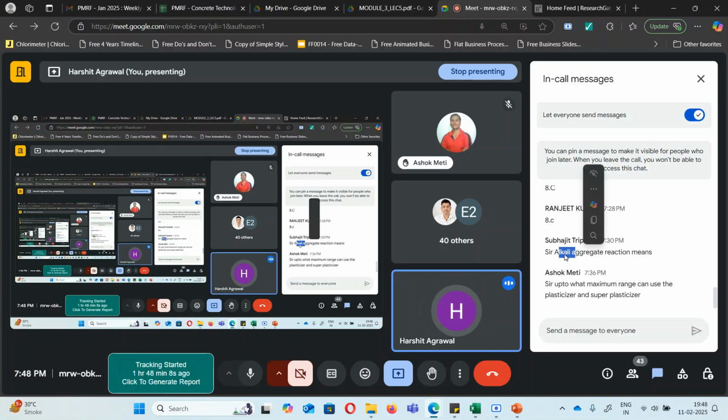Alkali aggregate reaction we'll see when we talk about durability. It is basically alkali which is present in the pore matrix due to cement hydration. When it reacts with aggregate, it causes gel formation. That gel is expansive in nature, which can cause cracking in concrete, and that reaction is known as alkali aggregate reaction. So if my aggregates have reactive material, reactive silica in it, it can give rise to alkali aggregate reaction. More on this we'll see when we talk about durability, so that you are clear with what is cracking and what is happening in the system due to cracking.